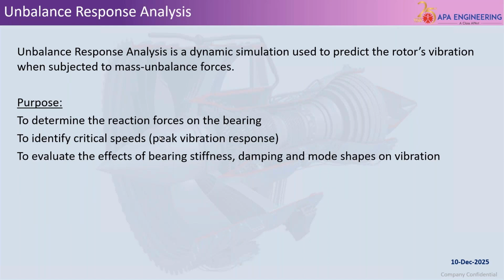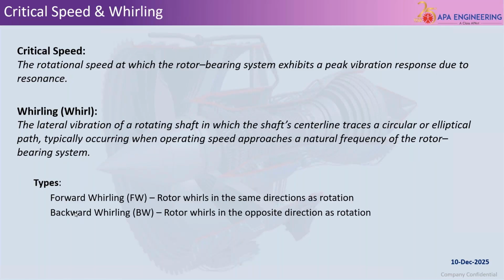And we can also evaluate how bearing stiffness, damping, and mode shape are going to influence the vibration levels. So these are some of the purposes of an unbalanced response study. In short, the simulation helps us see how the rotor behaves across a wide range of operating speeds, so that we can ensure safe and stable operation. I will introduce a few concepts: what is a critical speed, and what is whirling.